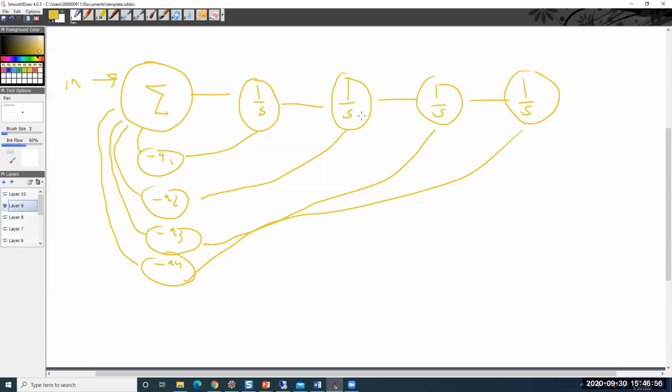Okay. Now, inside of this is really this. Okay. So inside of each one of these is an inverting integrator. But notice all of these need to be inverting. And so what happens is this is actually minus S, which is, then I don't want to invert it. This would be minus times minus positive 1 over S squared. I do want to invert it, and so on and so on.